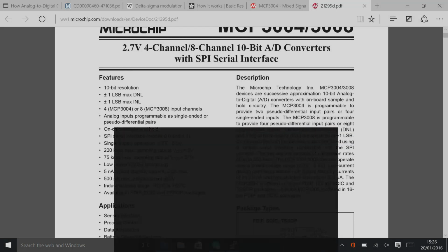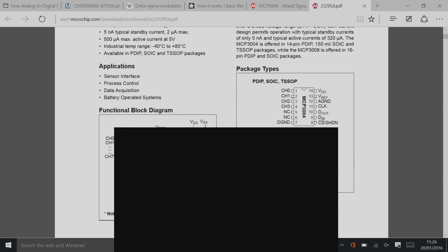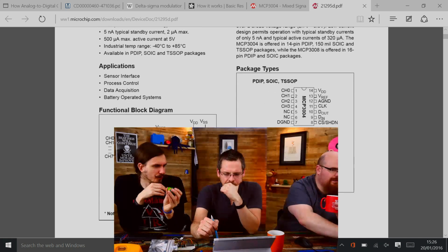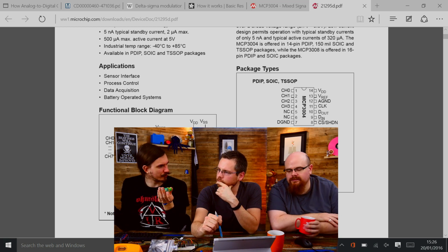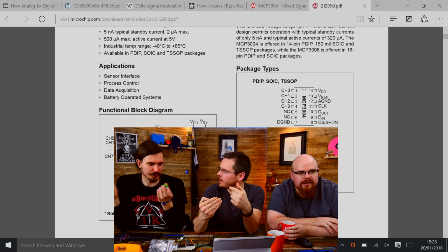You say you have an interrupt on your ADC where it'll tell you that it's got a value. That's interesting, what we use in the Flotilla modules when we're reading ADC values. It will start a reading and then it will go off and do something else, like talk I2C to the dock. Talk I2C to the dock, yeah.